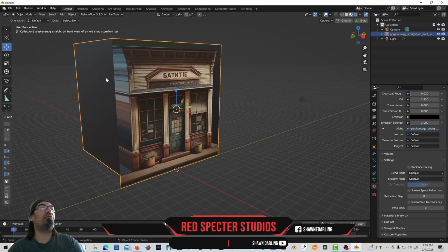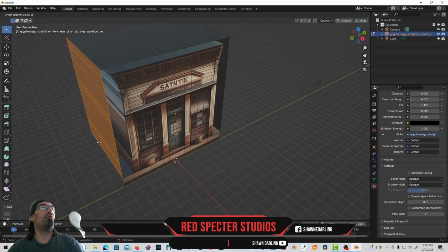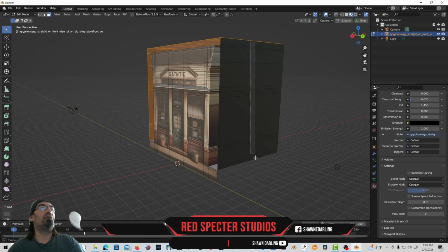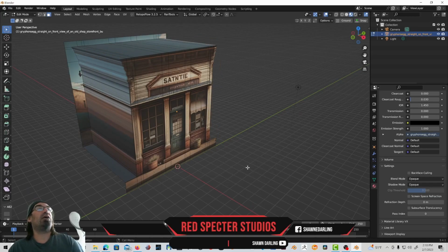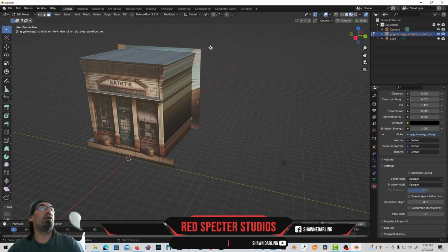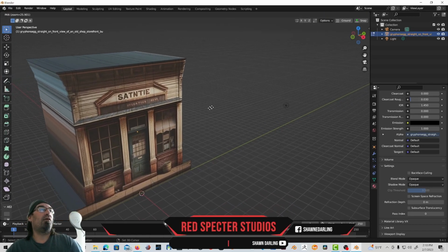It looks like it's in a box now, so we just need to go back into edit mode and delete these extraneous, my favorite word, polygons here. The offending polygons. We can take those and just delete and say faces, and now we're left with this. Yet again, we can take these entire edge ones here that we started with. In fact, you can leave the ground ones for now, it's all right. But we're going to take these and get rid of those too. We can now delete them and just say faces. So we're left with this.